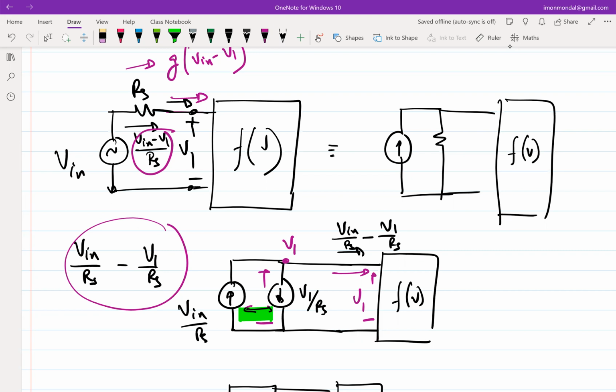So let's say I replace this RS with a diode. So in the truest sense, in the full nonlinear sense, I cannot do this. But in the incremental sense, can I do this? I can do this. I'll be replacing the diode with its resistance, and the current-voltage relationship across the diode and through the diode is essentially linear. So I can do this step. If I had a diode instead of RS, the capital I, capital V replacement wouldn't have been done, but the small i, small v replacement would have been done, right? The incremental replacements I could have done.